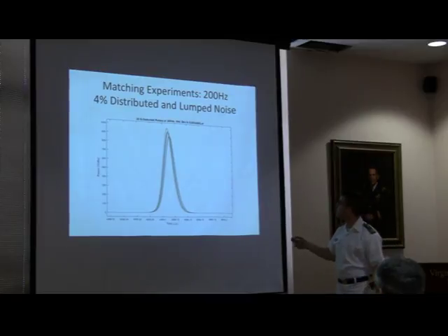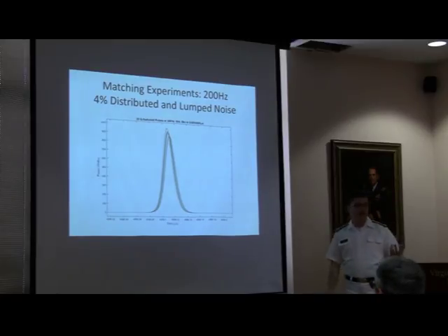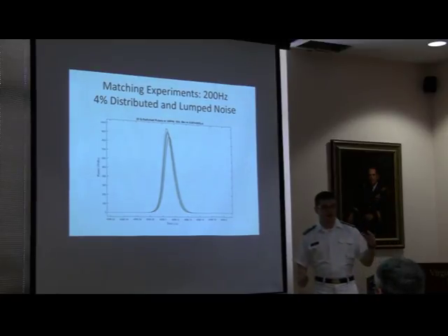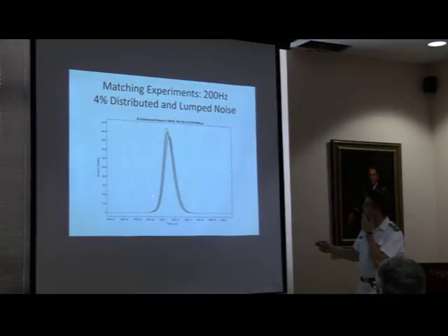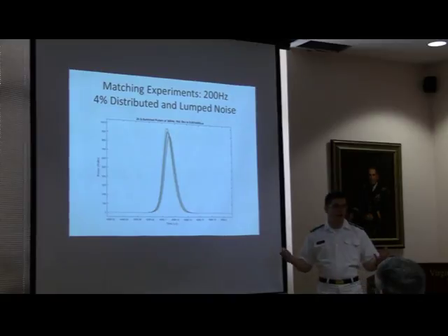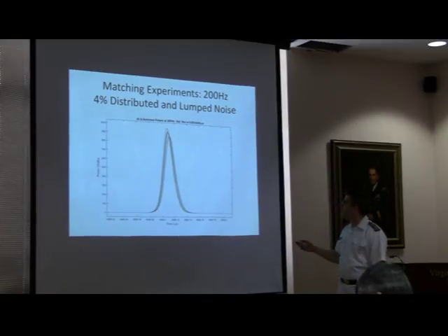And up to 4%, standard deviation didn't change so much. It actually went down a little bit, which could just be an effect of running it multiple times. I mean, this is stochastic in many ways. This is not the same pulse train every time. If you run it enough times, you're sure to find at least a couple outliers eventually. That's just how this works. But we're getting a better spread. We're getting groupings around the periodic noise itself, which can happen. But that's really about what we figured out right now.